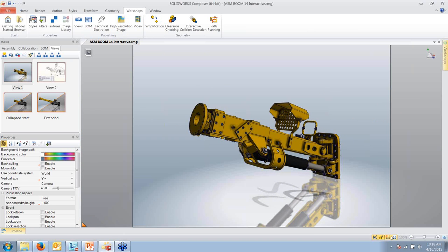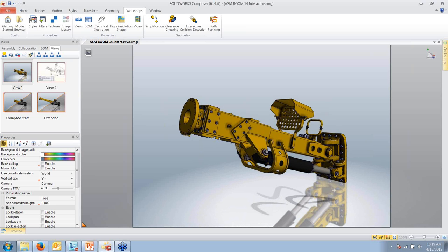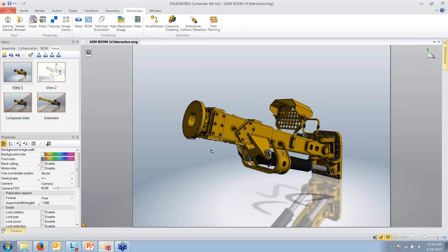But for our purposes right now, this button on the left is design mode. And we can toggle between those, and that's actually going to activate between design mode on or off. So if we turn design mode off, we're going to be interacting with our document the way a user would. So we don't have to save it, open it up in Composer Player to see what they're going to be dealing with. We can just go over here, turn off design mode, and now, minus this other stuff around here, inside here is what the user would be seeing and be able to use.